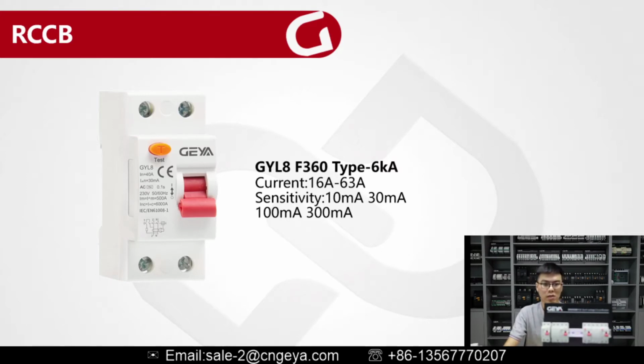And the sensitivity I have introduced, we have some different levels. So we can do 10 milliamperes, 13 milliamperes. These two are high sensitivity, and the medium sensitivity is 100 milliamperes, and 300 milliamperes is for low sensitivity.